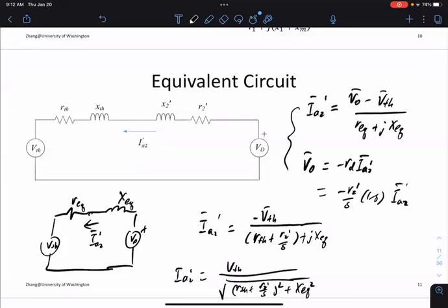So this is the current computation we have. Normally this current computation is something you do first. After you figure out S, you figure out the current, and all the power can be computed through this current. Everything can be computed here, either through the complex current or through the magnitude of the current. Questions about this?